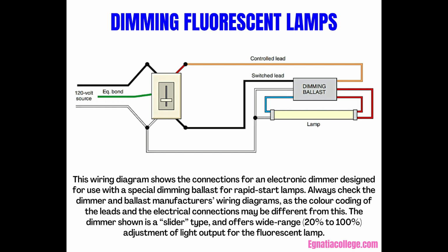Fluorescent dimming ballasts and controls are available in many types, such as simple on-off, 100% to 1% variable light output, 100% to 10% variable light output, and 2-level 100% or 50% light output. Wireless remote control is also an option.